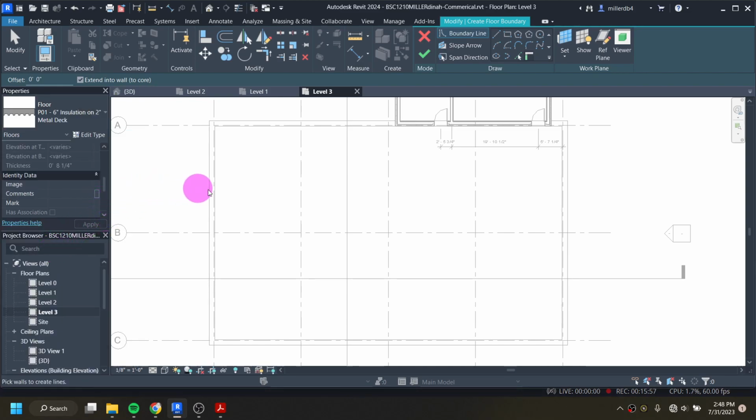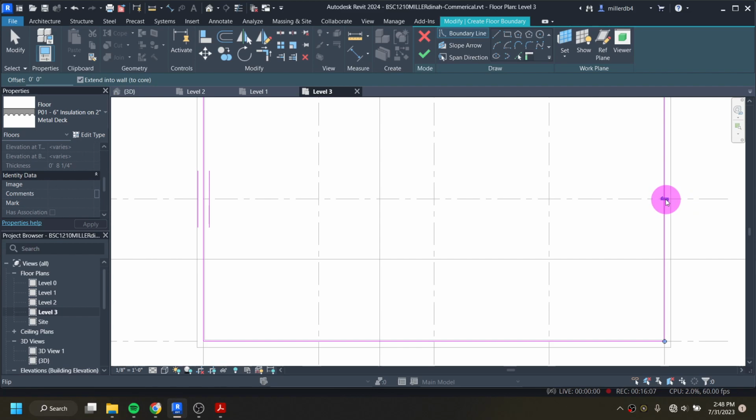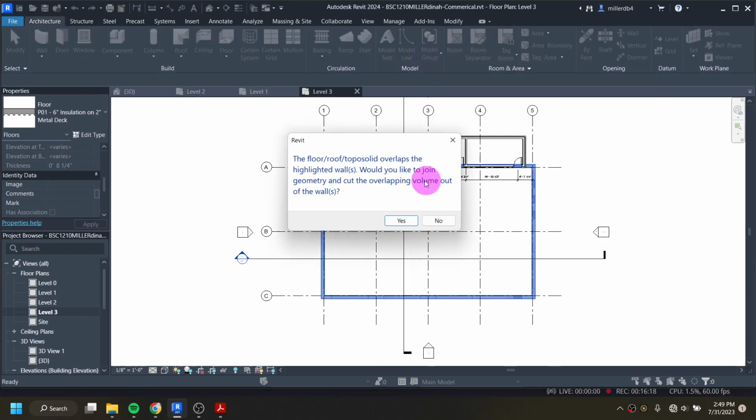And I'm going to, again, use my pick wall tool. Our roof is going to be as simple as just picking those 4. If it did extend to that outside of the boundary, we're just going to click to put it on the inside, so you could just use that arrow to flip it. And then we will say finish.